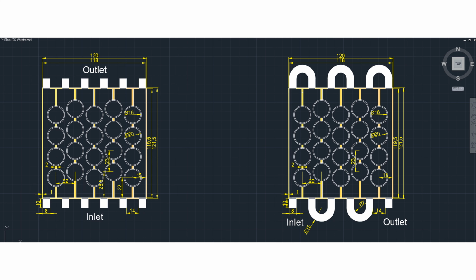So let's proceed with the fluid flow Fluent option. Open with the geometry part. So let's go with the new design modeler geometry. As per the geometry which is available to us, this is one of the things which we are going to follow. First of all, setting the units, I will set it to millimeter. Click on any one of the plane, XY.